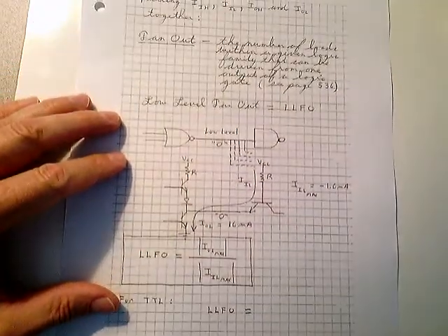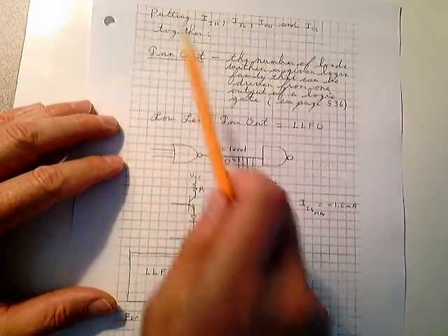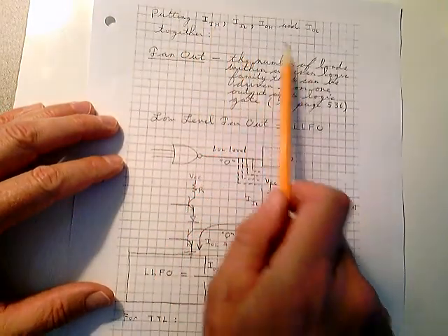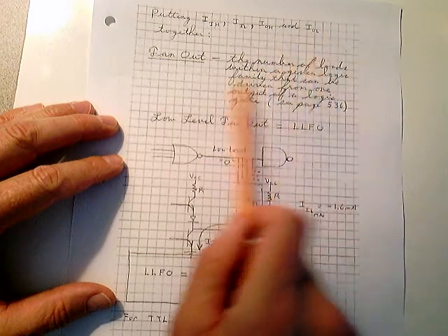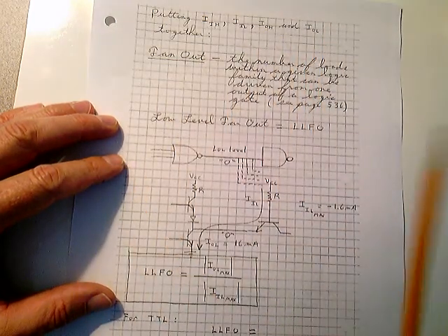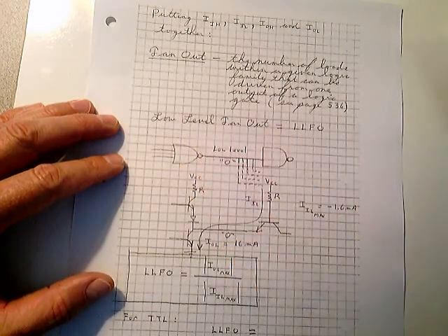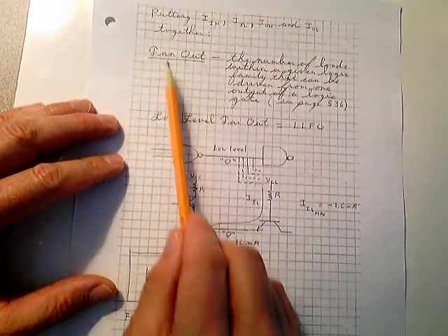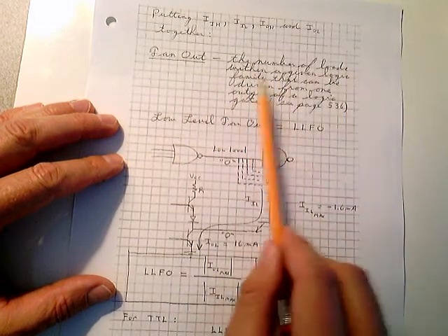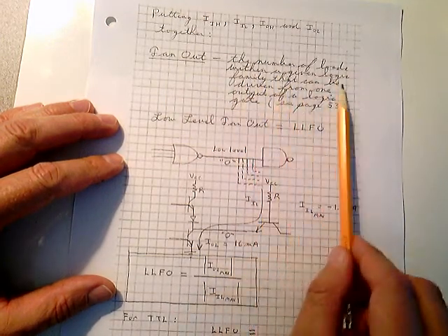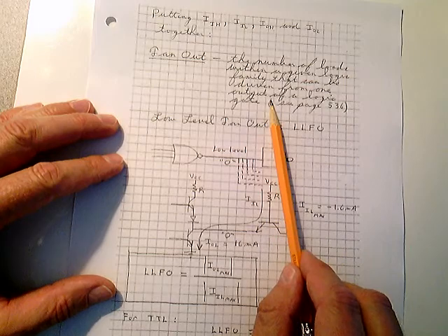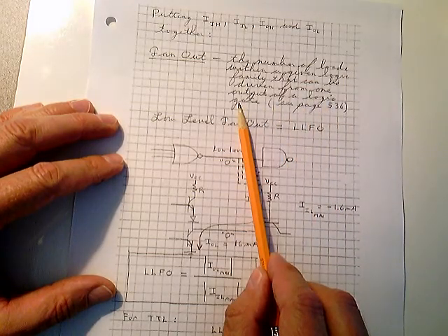And then finally, on page 140, let's put IIH, IIL, IOH, and IOL together. Well, all the voltages went together and they formed noise margins. Well, you don't form noise margins with currents. You form fan-out. What's fan-out? Fan-out is the number of loads within a given logic family that can be driven from one output of a logic gate. Remember I told you this before, that you cannot do this.